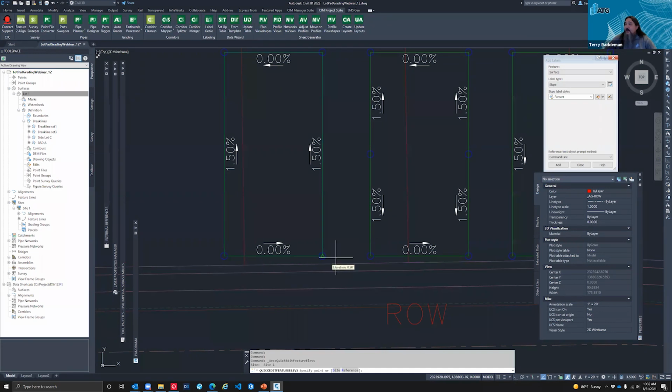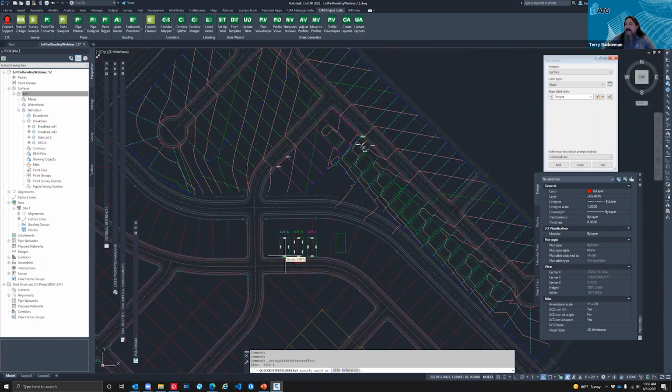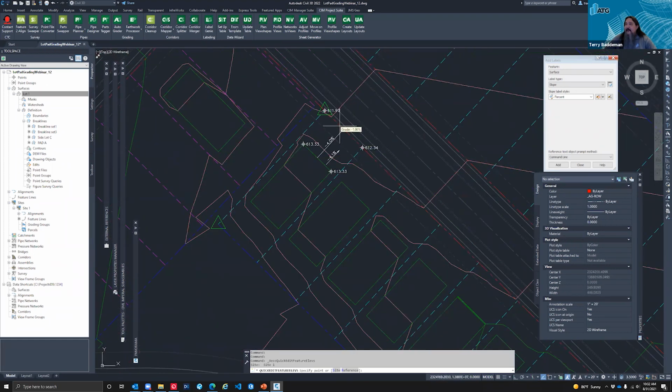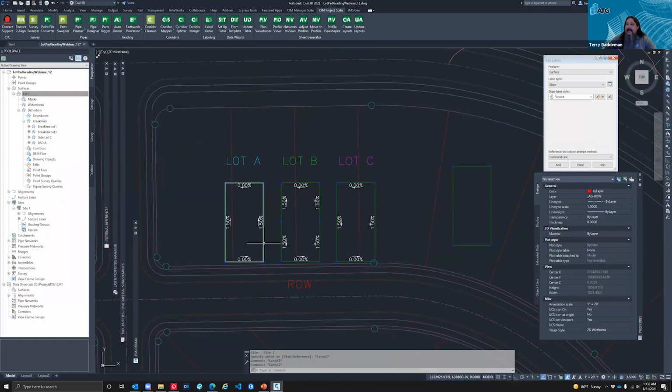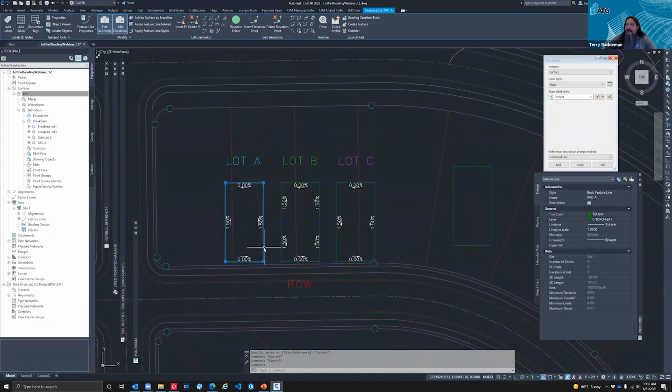It's actually lower or higher because it's sloping up. So this is at 0 and this is at 0.9. What it's doing is this front line is relative to the elevation. So if it's higher than our control line or our parent feature line, then we're going to get different slopes here. So what we can do is take this guy and just lower it by point nine.